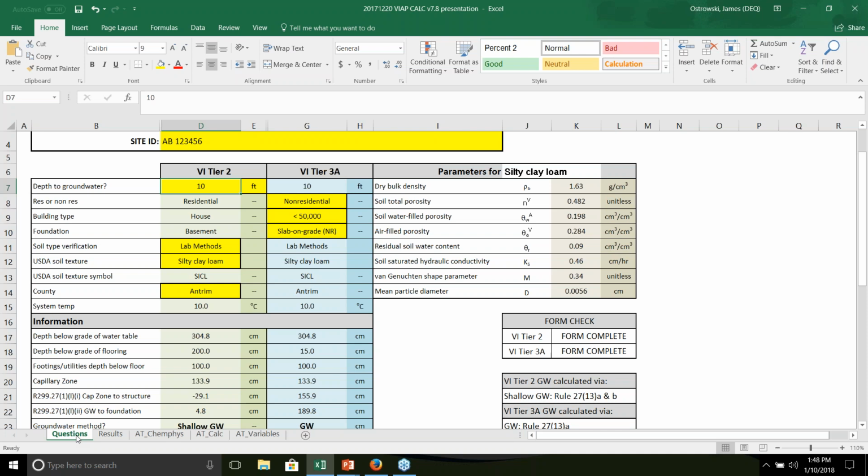So for existing projects where soil sampling has been complete, there are other PowerPoints that we have. We can send you additional information. The question is, why can't the DEQ come up with a conversion from the USCS to the USDA? The answer is, and we can provide you the references, if you look at what the U.S. Army Corps of Engineers did for a comparison survey, they compared hundreds of samples between the two classification systems and established very conclusively that there is no correlation between the two. There is no way to correlate one to the other, especially when we were trying to make generic criteria that are applicable and that everybody would get the same answer for. So it's going to be important to use the USDA classification system.